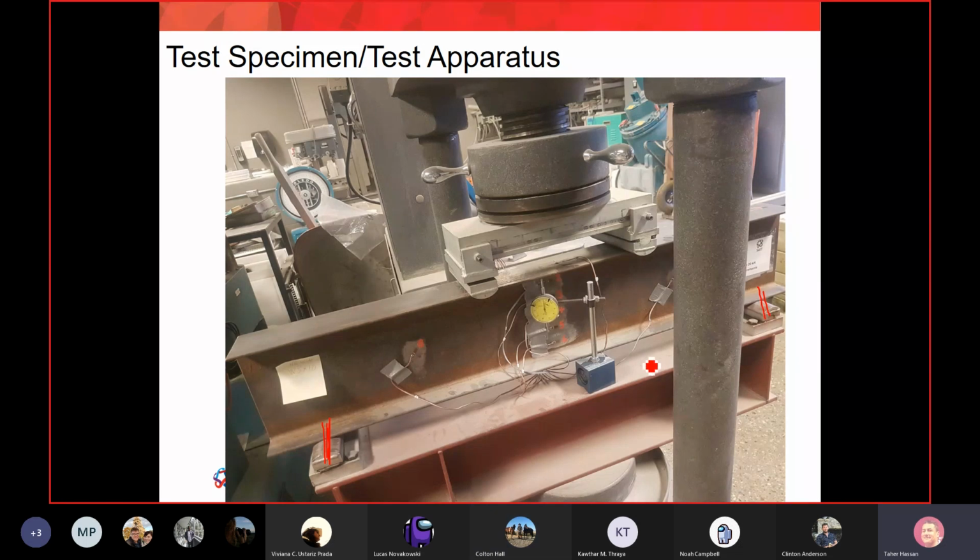Yep. Okay, do you see also the strain gauges? The strain gauges are connected using wires. All those wires you can see here, for example, this is strain gauge number 8, and you can see it close to the support at a 45 degree angle. And number 9 is hiding behind the column. So it's over there, and it's also at an angle of 45 degrees.